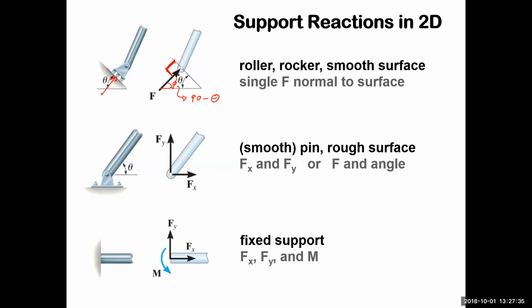You might also find a fixed support. That's where you just bury that whole support into a wall or something, right? And a fixed support, because the thing is embedded in here, is not only going to offer an Fx and Fy, but also a couple moment. And the couple moment comes from, it's kind of interesting when you think about what's happening.